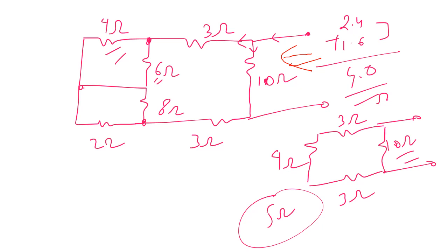This resistance and this resistance are in parallel, so this will contribute 1.6 ohms. These resistances are in parallel, and they will contribute 2.4 ohms.